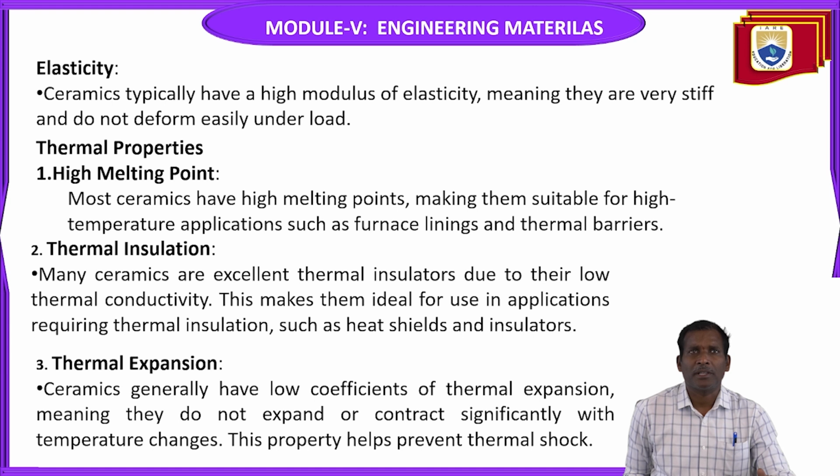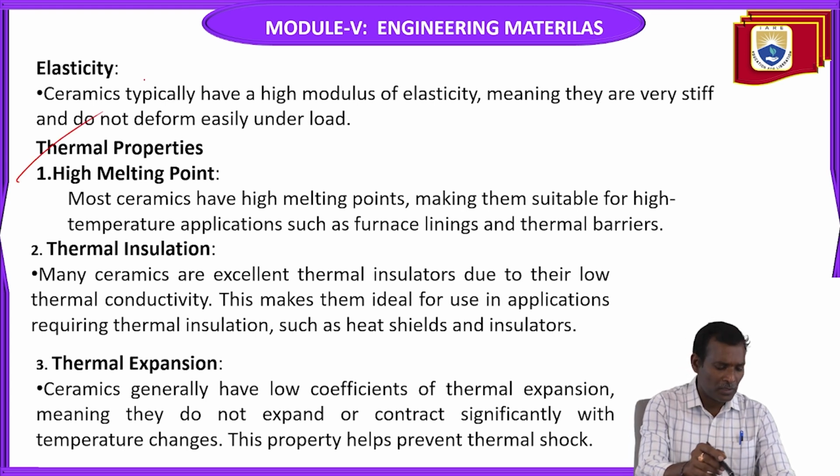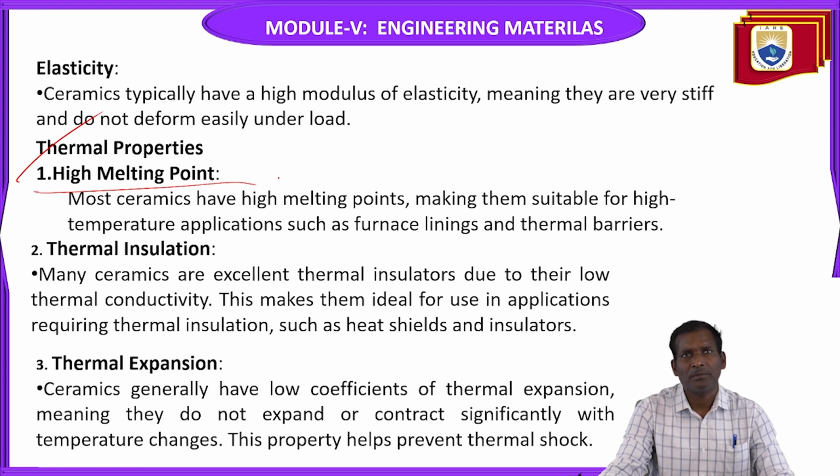Next, elasticity property. So these ceramics typically have a high modulus of elasticity. So meaning they are very stiff and do not deform easily under load. And then thermal properties. Thermal properties are high melting point. So most ceramics have high melting points, making them suitable for high temperature applications such as furnace linings and thermal barriers.